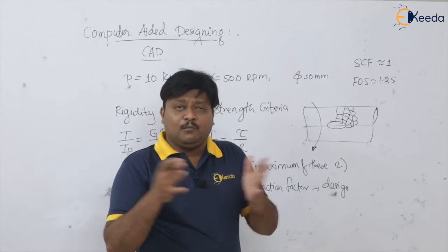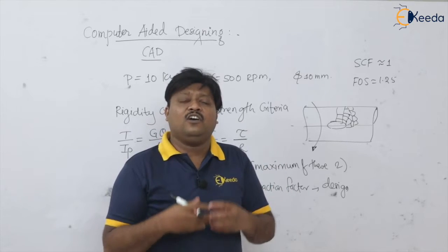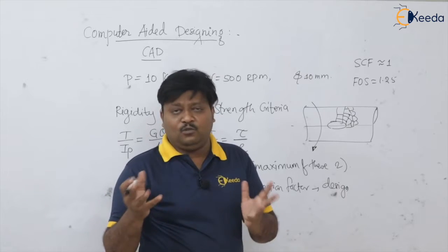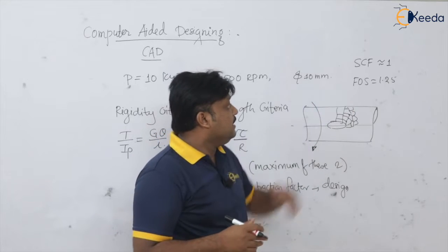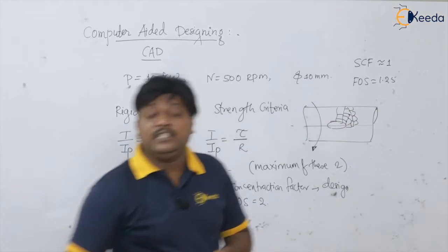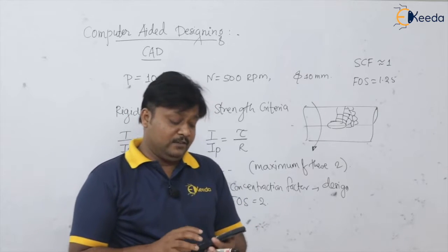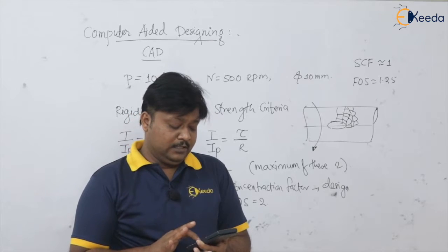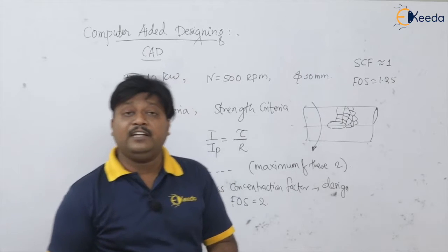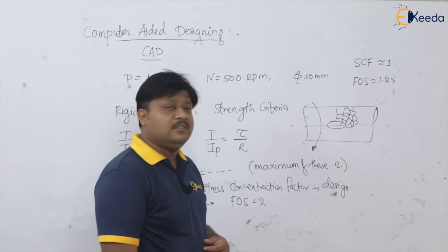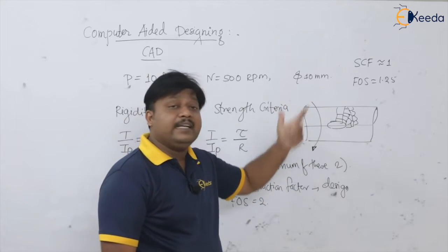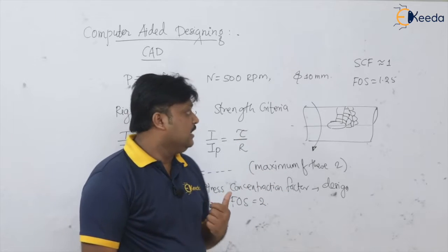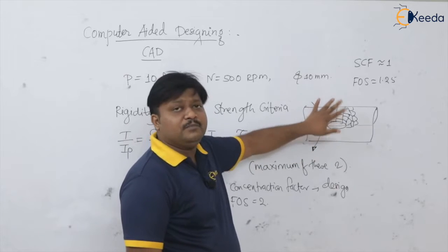So whatever the amount of material, the designing cost, manufacturing cost, all these are wasted for the next 4 tons. Yes, no doubt, factor of safety we have to consider, but see here, when the factor of safety comes down to 1.25, I can guarantee that the customer can use that same crane hook up to, say, 8 divided by 1.25, up to 6.4 tons, or around 6.5 tons. I can give him the conditions for the use, isn't it? So like that, definitely factor of safety is going to decrease.